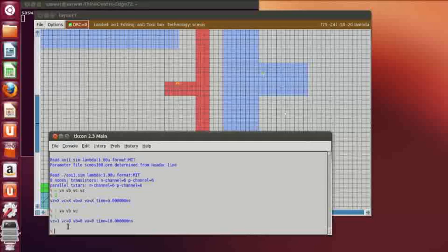It's showing VA, VB 0 0. So when A is 0, B is 0, this is A dot B, output is 0. Then we have OR. This is the AND output, then this is the OR input. So the total final output will be 0 again. So this is AND OR invert. So whatever the output from here, we'll get an invert of that. That is, we got 1.